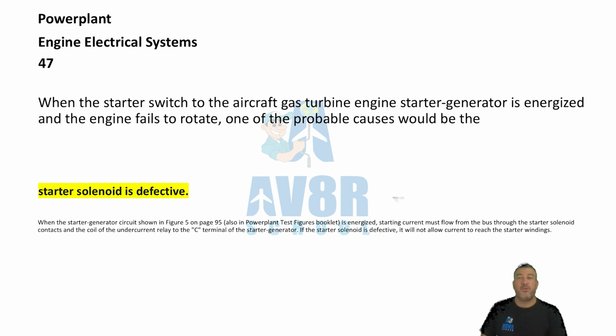Don't let them try and mess you up. If you have a starter on your airplane and you push the button to energize it and nothing happens, take a look at your starter solenoid. It may be defective. Don't overread these questions. They give you a lot of bogus stuff.